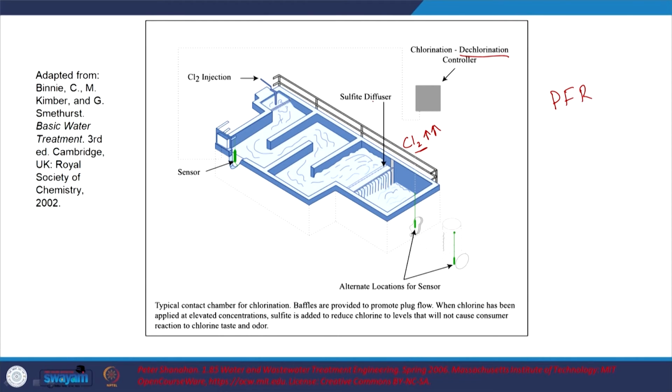It was that the municipality was pumping in more chlorine than was necessary. We will look at why they add more chlorine in the first case. So, if the chlorine is too high, you want to dechlorinate. That is why you want to add a reducing agent to be able to reduce this oxidizing agent, which is chlorine. So that is what you see, right, a typical plant. Yes. So, let us move on.